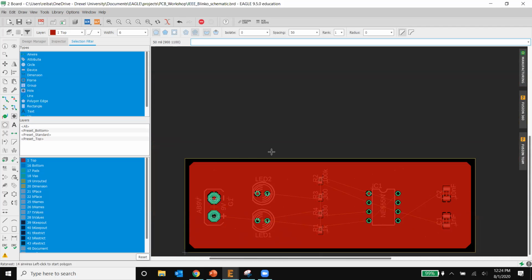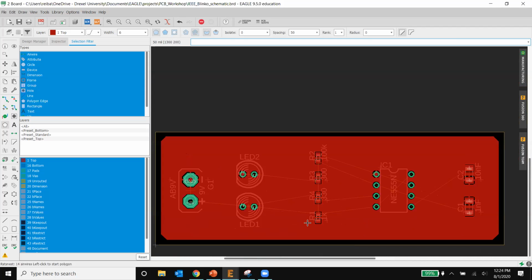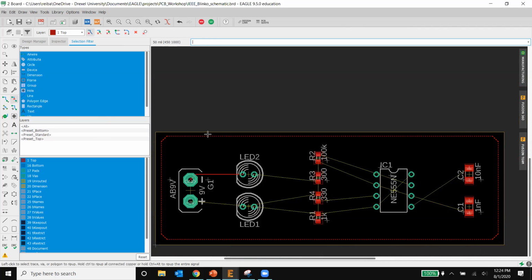So that's why things relate right now, why we use supply and why we use GND. So it's a helpful tool. Now, but we don't want it because we haven't finished yet. So what we do is we go to this rip up, and we have this tool. Don't press this. This is you deleting every signal, so you're killing your work. So don't do that. You're gonna press all visible polygons, and you're gonna end up like you were in the beginning, which is better.